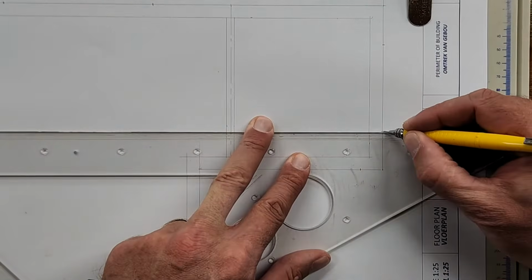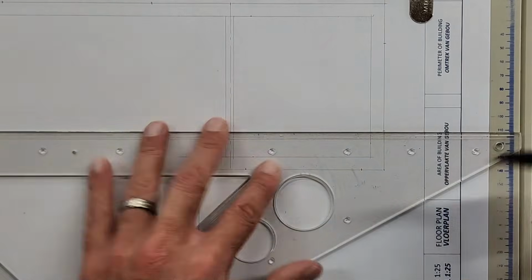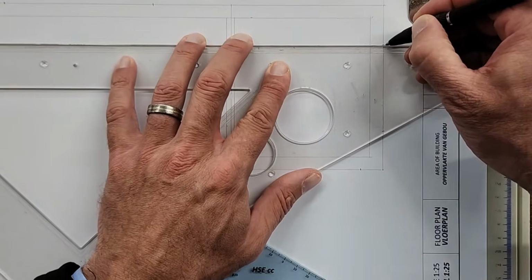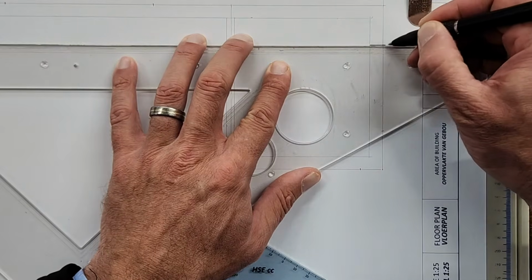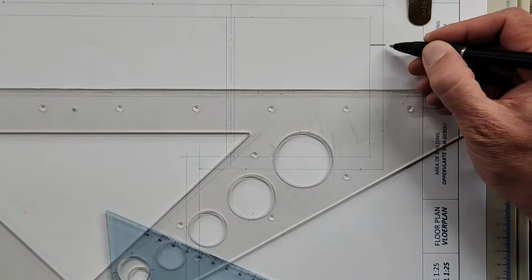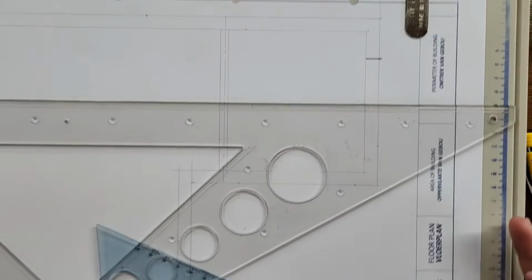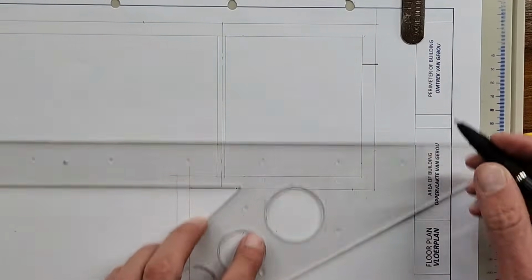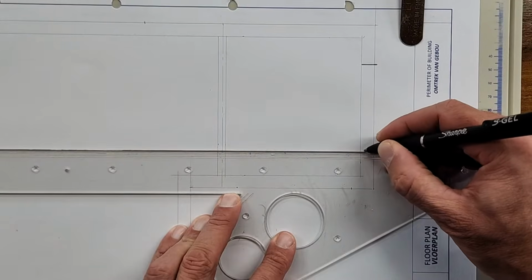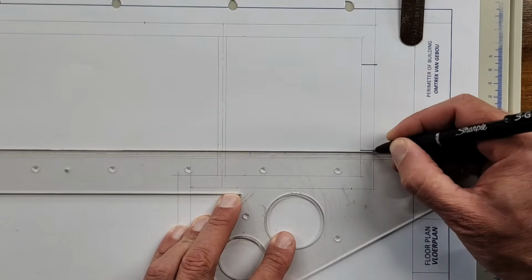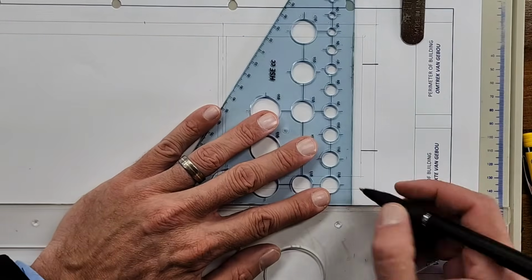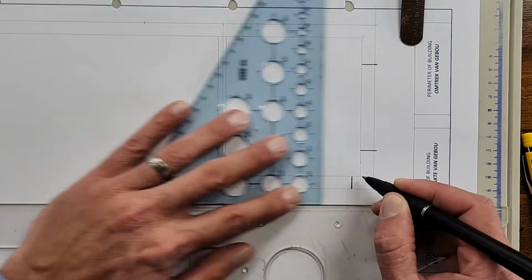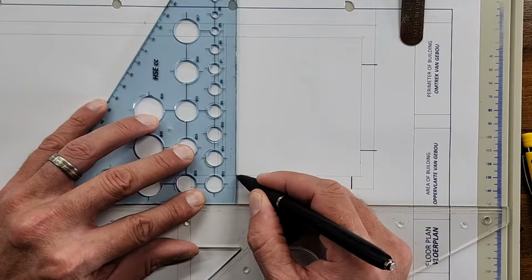We're going to have a solid line. Maybe can I do this in another pen so that you guys can really see it. So I'm going to, you keep with your pencil. And we're just doing, at the window here, about a 2 millimeter extension because we're thinking of that window sill that needs to be indicated. And after a while, you actually get to a point where you can estimate that. The actual doorways, it starts and stops on both ends.